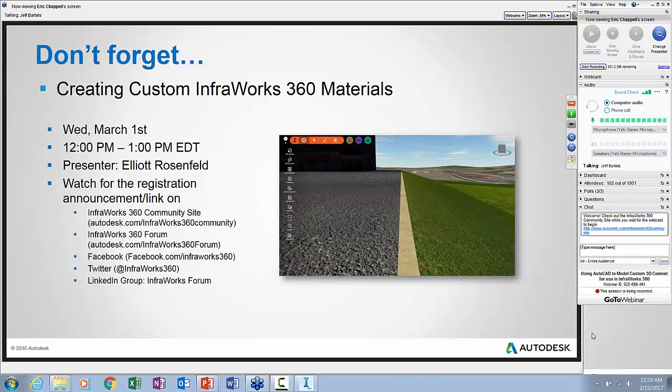What I do is I define my materials. If I'm in AutoCAD and I've got a shape, let's say it's 4 feet by 4 feet, when I define my imagery that I'm going to put in there in Photoshop, I'll say I just make it 4 inches by 4 inches at like 200, 250 dots per inch. So it's proportionally the same size. When you create the material, in the material, you scale it so that it's the same size as the face that you're mapping it to. That's when it gets scaled.